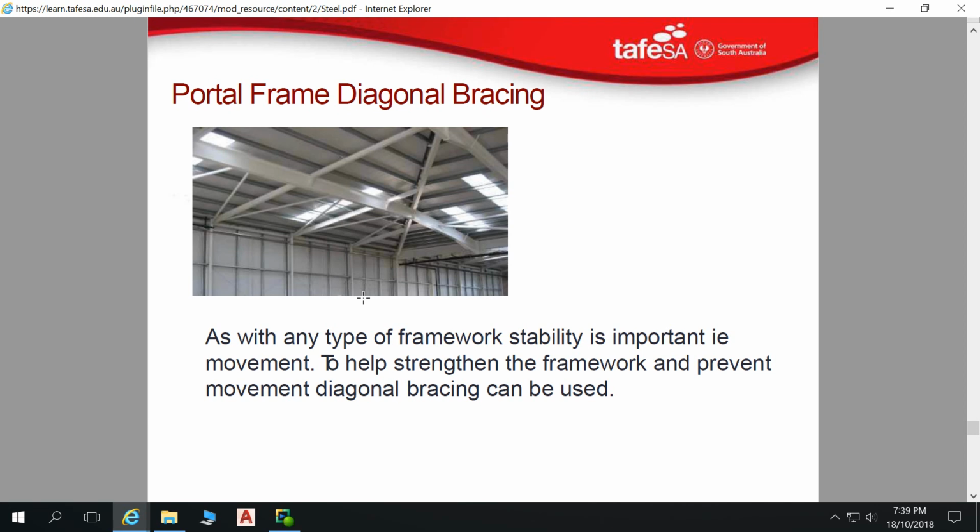In the other direction, we can actually remove that bracing and put in a solid piece of, let's say, timber, something that works well in compression, or a concrete log or something like that. That is a strut. That will do the same thing. As the wind forces here, it's trying to make this shape instead, like that.